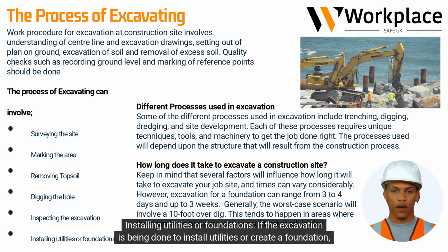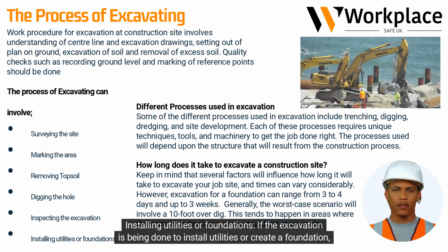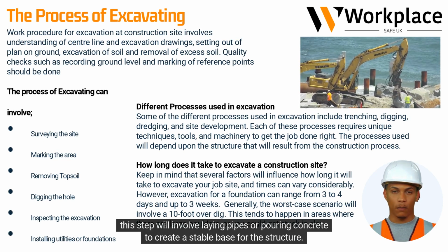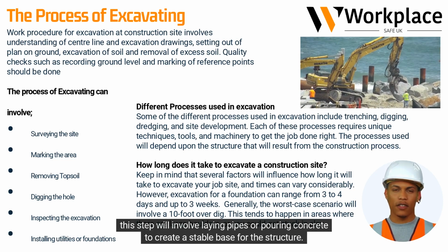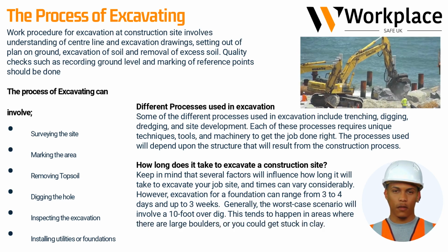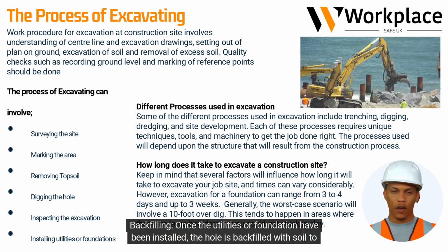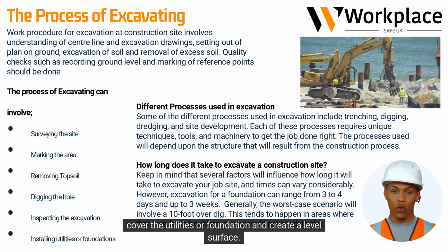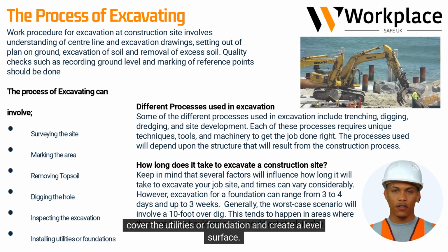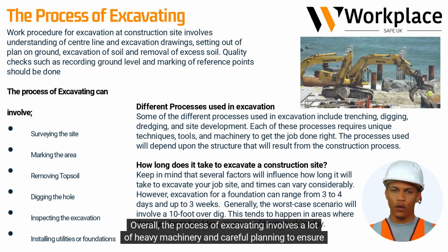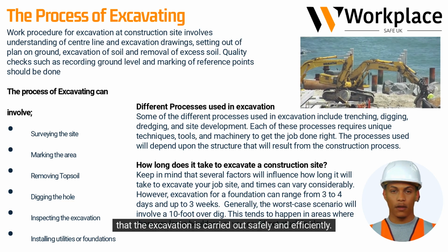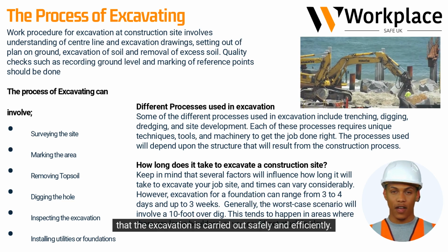Installing utilities or foundations. If the excavation is being done to install utilities or create a foundation, this step will involve laying pipes or pouring concrete to create a stable base for the structure. Backfilling. Once the utilities or foundation have been installed, the hole is backfilled with soil to cover the utilities or foundation and create a level surface. Overall, the process of excavating involves a lot of heavy machinery and careful planning to ensure that the excavation is carried out safely and efficiently.